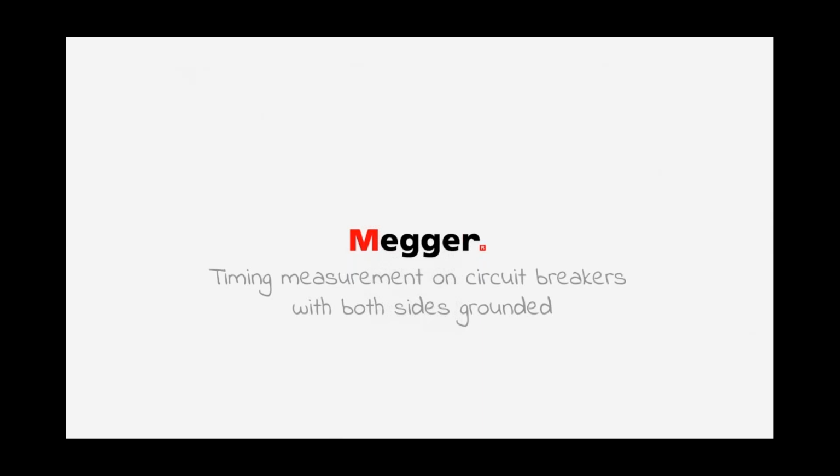Regarding the lubrication, just a second. Checking the quality of lubrication of, let's say, the low energy part of the mechanism, latch and so on, is quite important, because this is one of the main reasons of failure in, let's say, older generation circuit breakers.